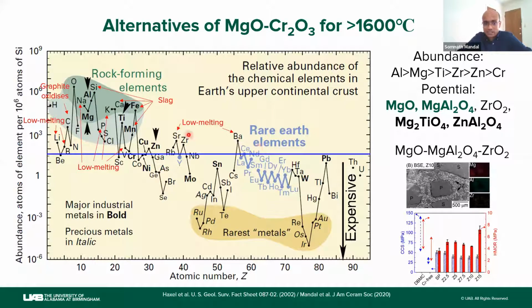And again, zirconium is a well-known refractory material. I found that if I want to make something which can compete with magnesia chrome, which is used in basic slags because almost 60% of the refractory is made of magnesia, then in order to withstand a basic environment, we need enough basic substance.